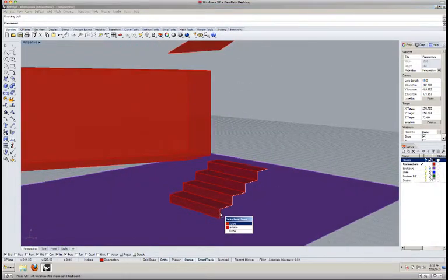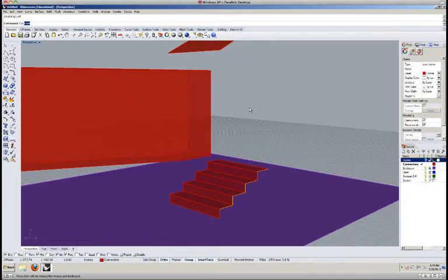I'm going to undo one thing. It's getting a little bit confused because there's a portion of line that's vertical, so it doesn't really know how to connect that to the top curve. So I'm going to do something that I did before. I'm going to take that curve, explode it, so that I can deal with each of the line segments individually, and deselect, hold down Control and click to deselect. Then I'm going to join this guy again.